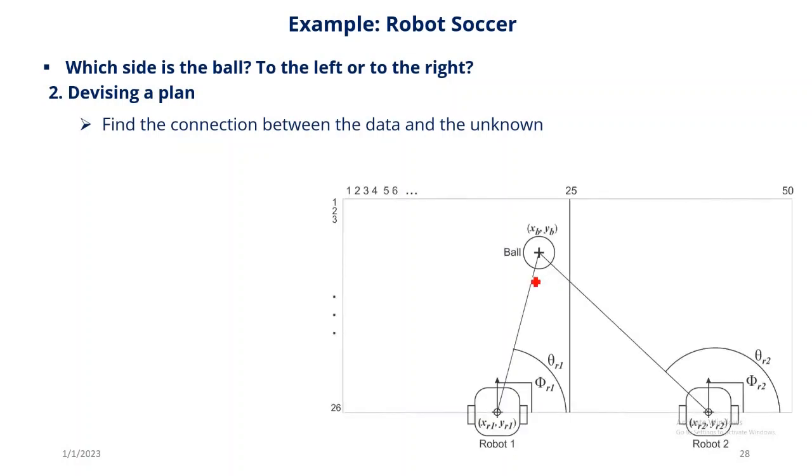So, what is our data? Our data are the positions of each robot and the orientation of each robot. The position is given to us by external sensors, maybe a camera that is looking at the robot, or something called robot odometry. You move the robot somewhere which is a starting point, and you tell the robot to move to a point, and the robot is using internal sensors to calculate its position, so it knows at this point it is here. Internal sensors with the assistance of external sensors. So this is data.